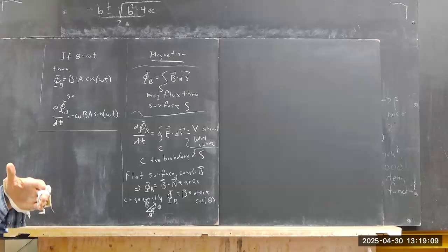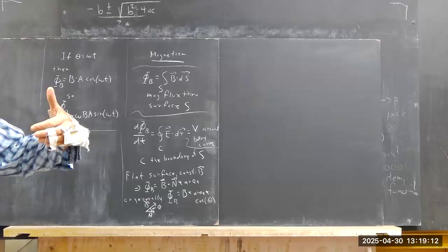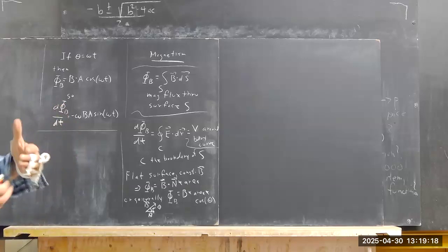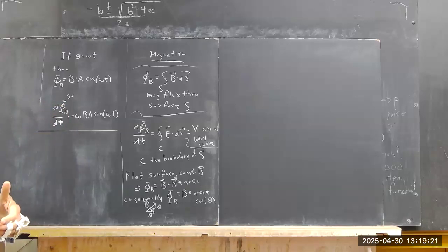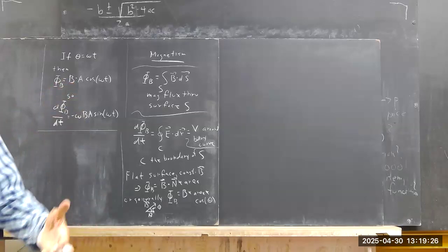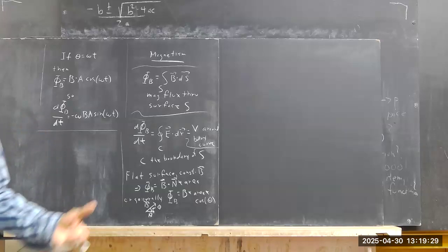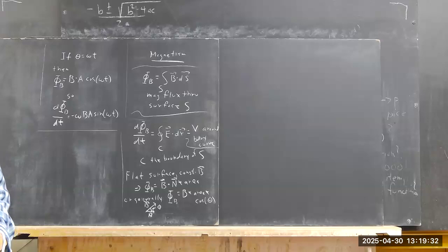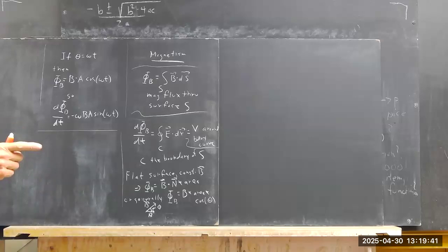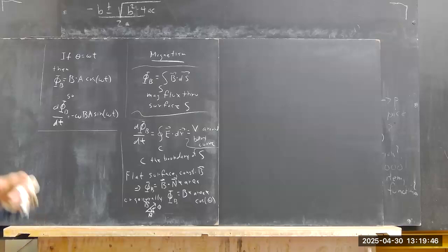That gives you a positive current, no matter whether you think it's positive or negative. It uses diodes and a clever operation: when the current goes this way, this diode cuts it off, but it goes through this other diode in the opposite direction, which makes it positive. You can look that up. The diode's just something that only allows electricity to flow in one direction. So with a clever combination of diodes, you can make that circuit into more or less a DC circuit.